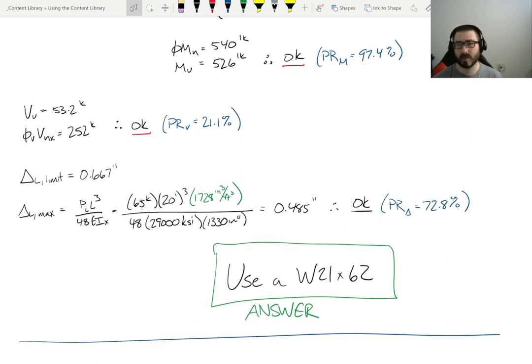And then next week, which is our last week of the semester, is really two things. We're going to have our final exam review on Friday, but Monday and Wednesday we're going to be tying up some loose ends. On Monday we're going to discuss designing for shear, computing shear capacity. Even when shear is a consideration, more often than not, even in bridge engineering, at least on a lot of the projects I've worked on, you're sizing the beam for moment and deflection, and shear is something you come in and, quote unquote, fix later with reinforcement, such as shear stiffeners.